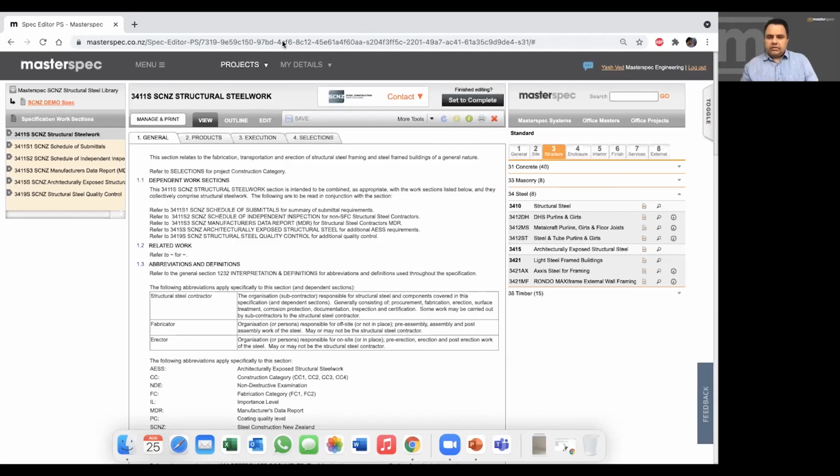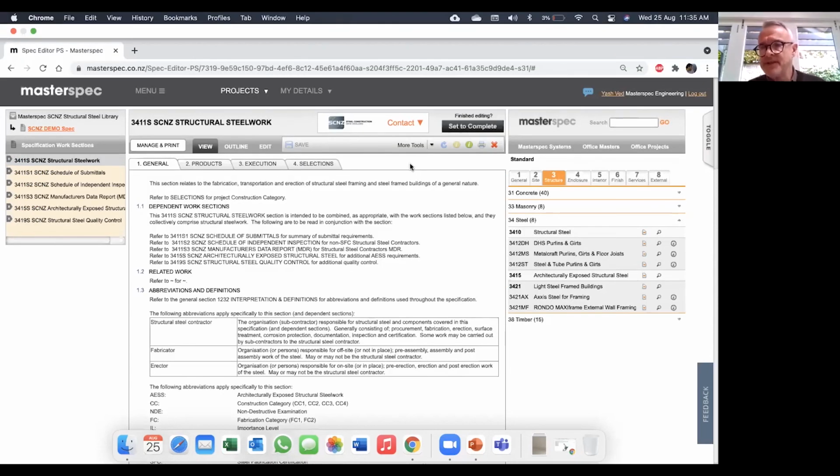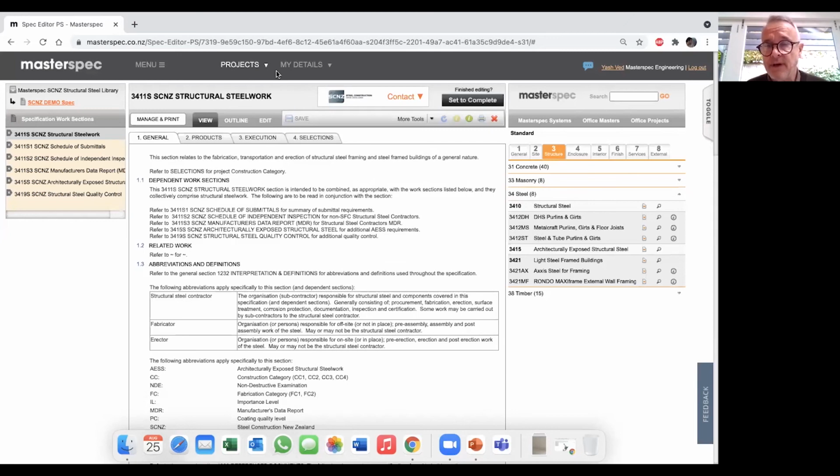Right. And if there are expansion joints, then you're going to have to treat those. You're going to have to look at those in terms of, every bit of steel has to be coated. And it might be a way in which the expansion joints are detailed, whether there's a cover over the expansion joint, which is in itself fire rated, or some other way of dealing with it. But expansion joints in intermittently painted systems have to be considered very carefully as to allow for the expansion, but maintaining the fire rating. Perennial problem. It's not easily solved.